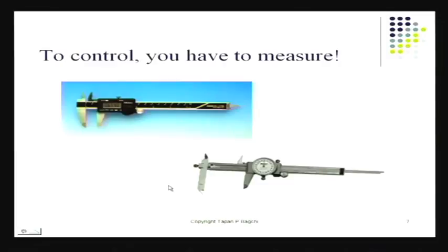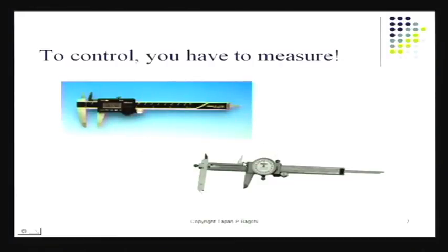For doing any of these things, you need to do some measurement, and it goes without saying that your tools must be good, your instruments must be good. If you're going to be using these for plotting control charts, you better make sure that the data collected are correct, and of course the calculations are also correct. To make sure that the data collected are correct, you've got to make sure you've done your gauge R&R, gauge reproducibility and repeatability study. So you've made sure that these instruments, which by the way measure dimensions, have been calibrated, and we know exactly if they have any drift or anything like that. So gauge R&R is the variability that is introduced by using the gauge as a measuring device, as something to produce data. That has its own contribution to variation in the ultimate data, and it must be kept within a very tight tolerance.